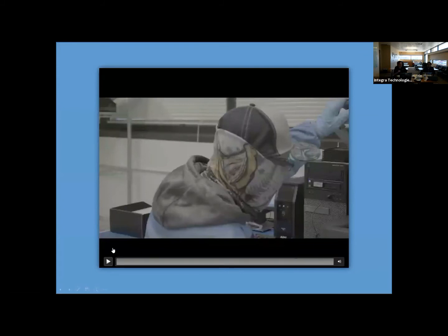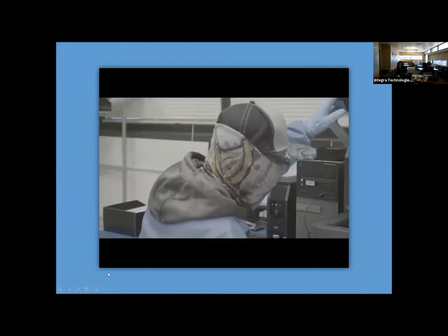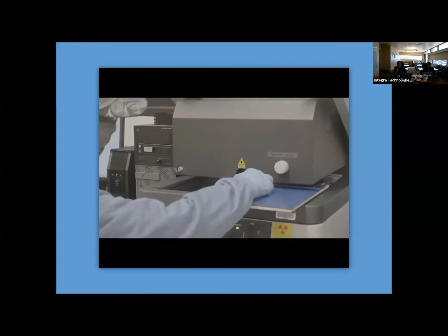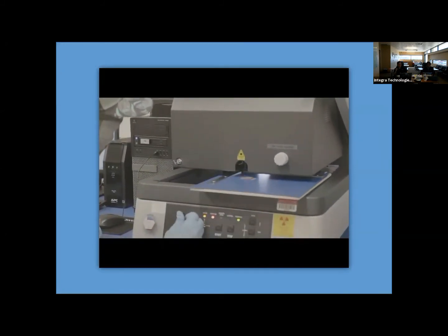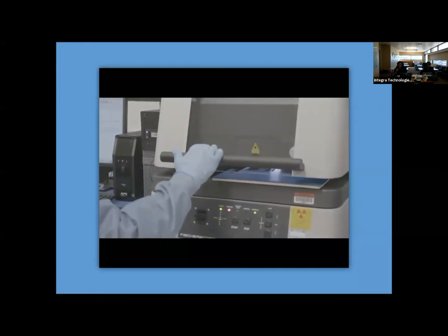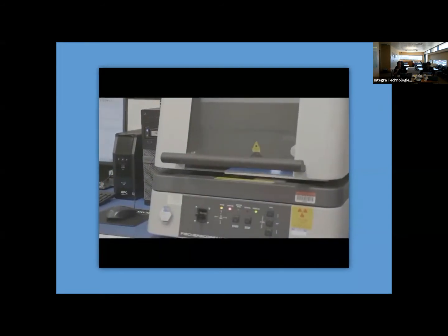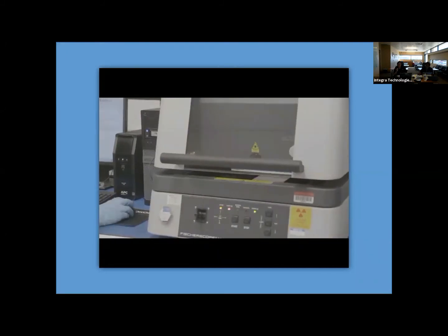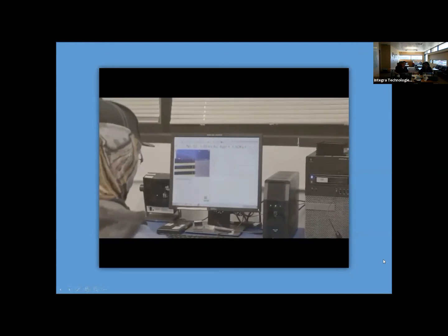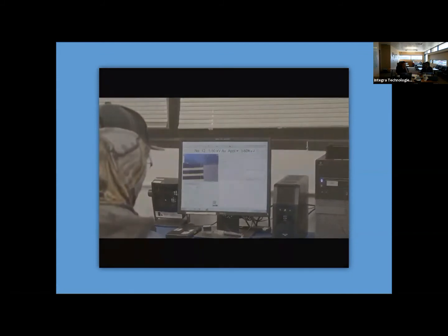So here's a video of one of our technicians performing XRF testing. XRF usually performs at around 50 kV. EDS, we can shoot at around 20 kV, so you'll get a difference in elements there. That's usually the main driver between the two machines in itself. So the tech put in the part, it's going into the machine, it's closed off, and you will see the part here in XRF, and he'll start to analyze.